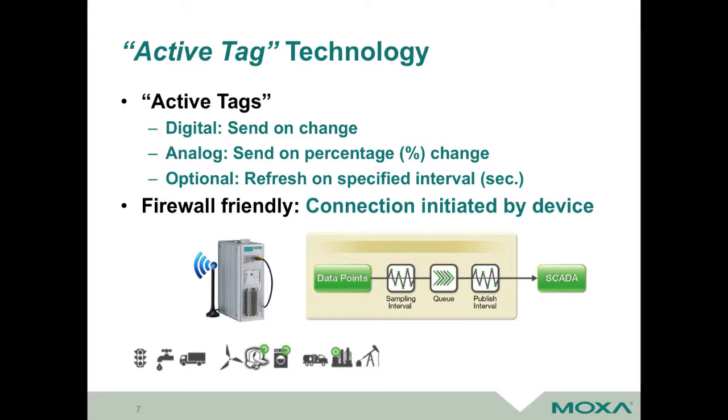applications with that. Now there are some technologies, and I'll talk just a moment about Moxa, but I think you'll see this being used across many different areas in the next 5 to 10 years. We've called this our active tag technology, and we've basically taken that report by exception down to the field level. So in a SCADA application, you will have a device out there that's able to collect that data, and then we use this in terms of an OPC server on the SCADA side with our connection here from device to OPC server, and that can do report by exception.